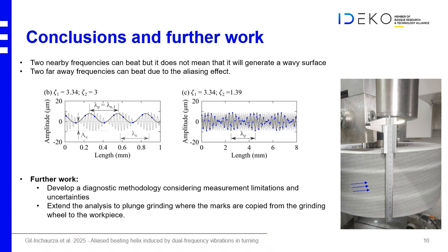As a further work, we would like to continue developing a diagnostic methodology that will consider the measurement limitations and uncertainties that we have. Very often we can measure a limited length on the workpiece, so we have uncertainty on the wavelengths, and this will cause uncertainty in the determination of the frequencies that can cause a problem. And also we would like to know what is the adequate or optimum measurement strategy to know which parameters should be obtained from the surface to make a proper diagnostic.